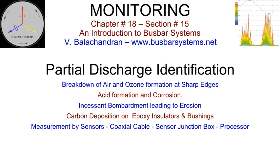Discharges in the vicinity of epoxy insulators and bushings can deposit carbon on the surface, thereby reducing the effective creepage distance, resulting in arcing and flashover. Partial discharge also generates a wide spectrum of high-frequency signals of varying amplitude. Online monitoring devices are available for the measurement of partial discharge.